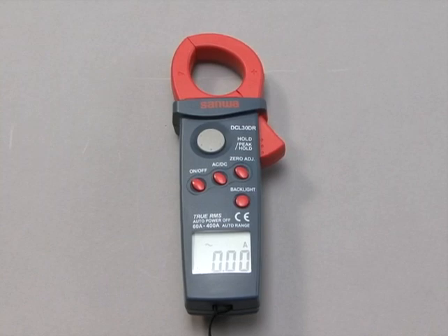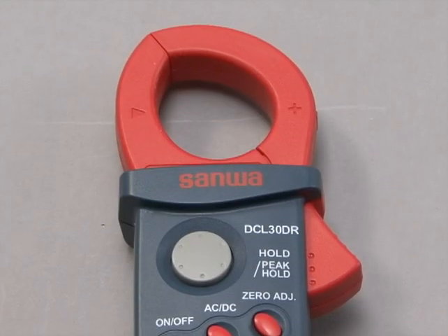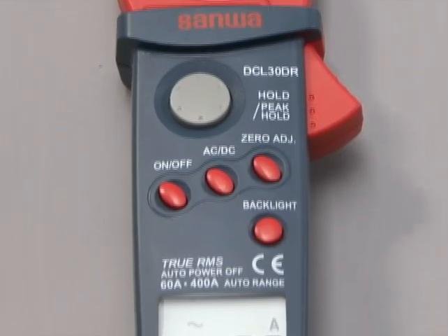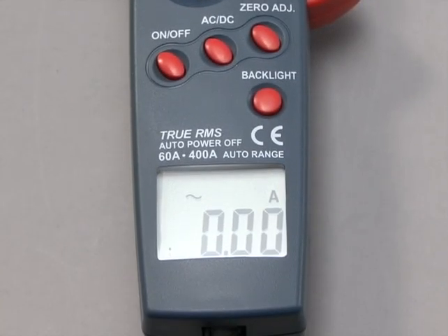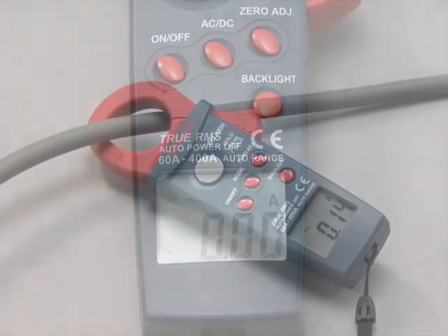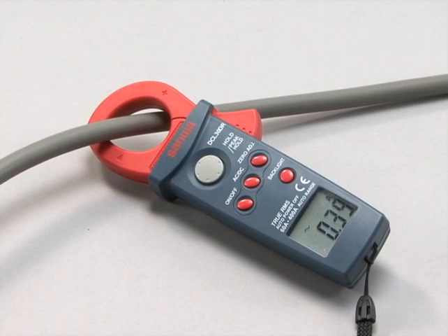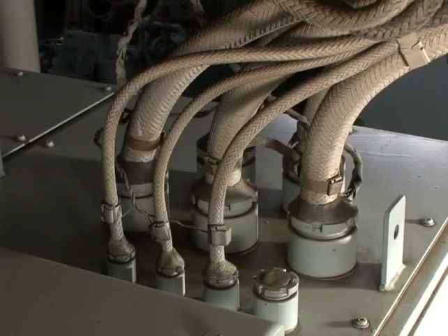It is possible to use a clamp meter to measure a heavy current like the one passing through the motor. Current flowing through the cables can be measured by a clamp meter without having to touch the cables. This means that current can be measured without having to turn off the equipment being checked. However, the clamp meter cannot accurately measure current flowing through basket-armored cables. Use this type of meter at parts that are free of armor.